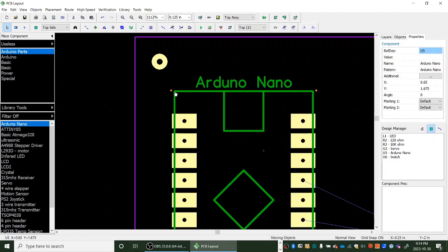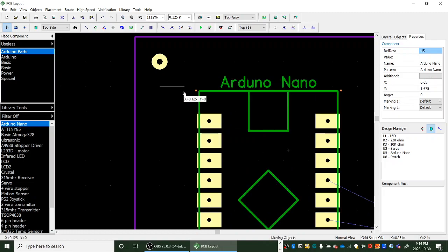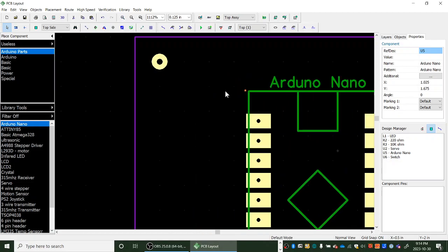this corner isn't going to snap to anything. If I snap there, it's not in the right spot. If I snap there, it's not in the right spot. So what we're going to do is turn on the grid size of 1/16, 0.0625, right there, that we created earlier. We are going to create a donut, another pad, at the location that we want. So 1, 2, 3 over, and 1, 2, 3, 4 down. So that's a 1/4 inch down, 4/16, and it's 3/16 over.